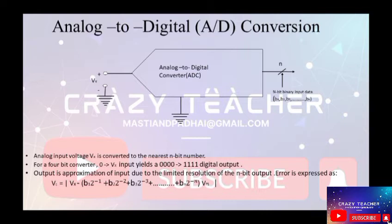So this analog input voltage Vx will be converted to the nearest n-bit number. Again the same thing: for a 4-bit converter, an input from 0 to Vx will yield a 0000 to 1111 digital output. When you give 0 as input, you get 0000.